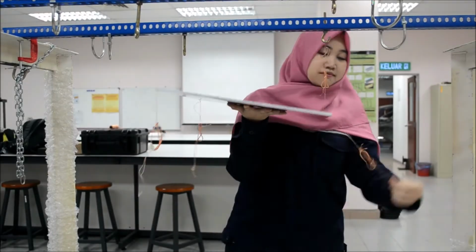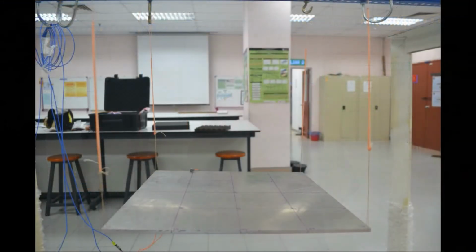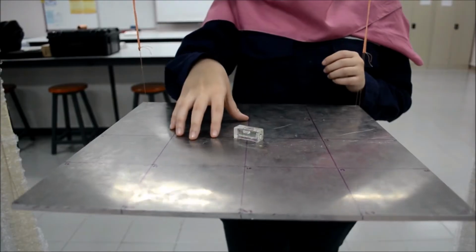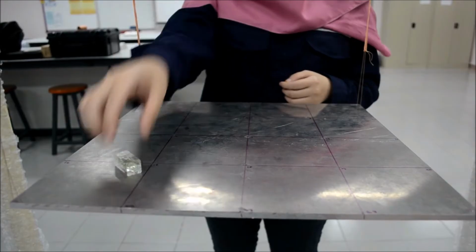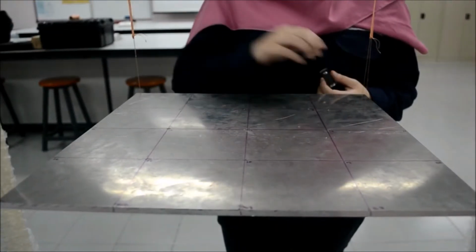Mount the thin plate structure with desired boundary conditions. In this case, the thin plate structure is hung by rubber bands attached at each edge to simulate free boundary conditions. Other supports that can be used include strings, springs, and many more depending on the structure itself. A water level is used to make sure the thin plate structure is at a horizontal position. Test to see if the thin plate structure oscillates freely by pressing it down. Free oscillations are important to avoid any external vibration from the hanging pole being introduced to the structure and somehow affecting